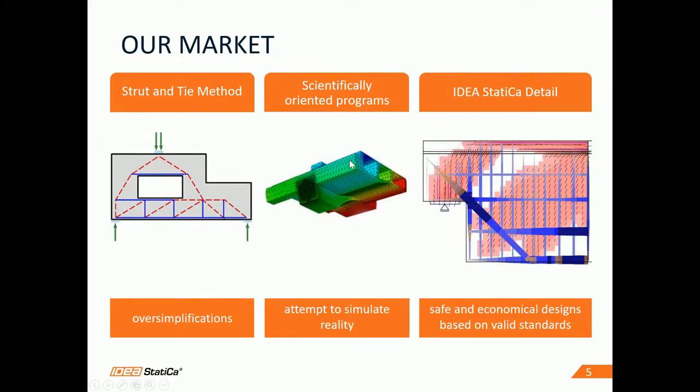Let me review the existing tools for design of discontinuity regions. Of course, there is the quite well-known strut and tie method and a lot of programs based on that. But probably, as you know, it enables only checking the ultimate limit state. You need to define a model of struts and ties, and unfortunately, nobody knows which model is the correct one. There are also scientifically oriented programs like Abaqus, Midas,